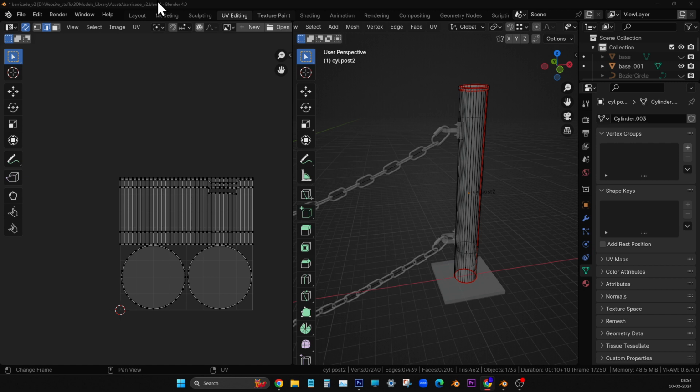So same thing, you have to do the connection for the top one also. Then immediately press Alt A. So go to vertex mode. Vertex mode. Yeah. You are feeling this gizmo as a bit. W, press W. Yeah, let it be. Now you can switch on the gray mode. Switch off the X-ray mode. Gray mode is on. Yeah. Now you can knife.